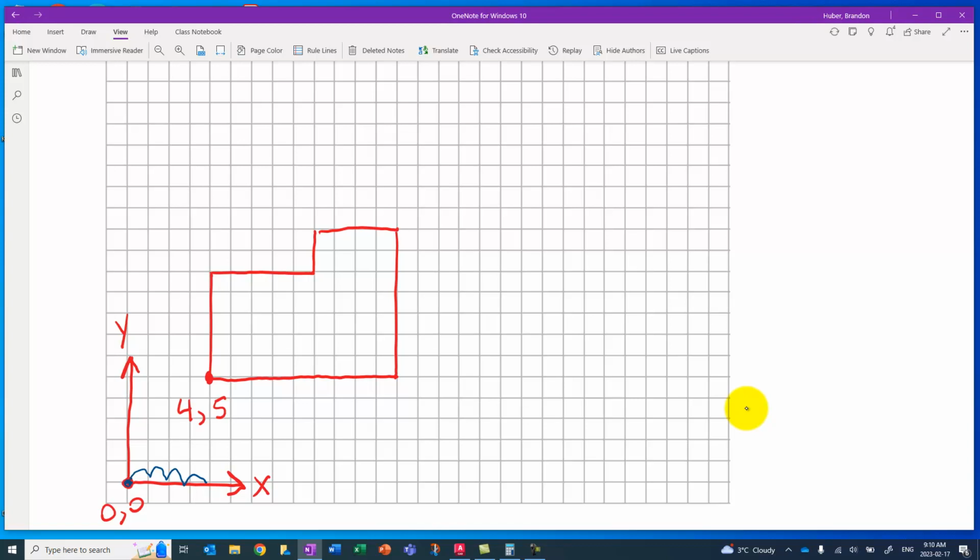Now, if we want to move to the right, to this point, just like with relative, we can count the squares, 1, 2, 3, 4, 5, 6, 7, 8, 9. But in absolute coordinates, what we will do is add the 9 to what the x-coordinate already was, because that will give us a distance from 0. So if we've increased in the x by 9, we must be at 13x, 9 plus 4, comma, and then the y-coordinate remains as 5.